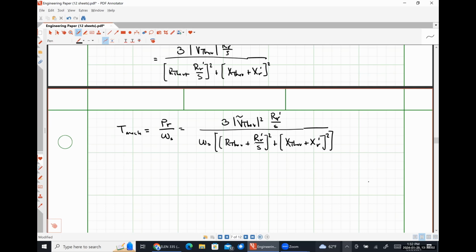What is the slip if our rotor isn't moving? Go back to your notes. We literally talked about this condition. So a slip of 0 means that the rotor is moving at the exact same speed as the stator field, right? A slip of 1 means the rotor isn't moving.